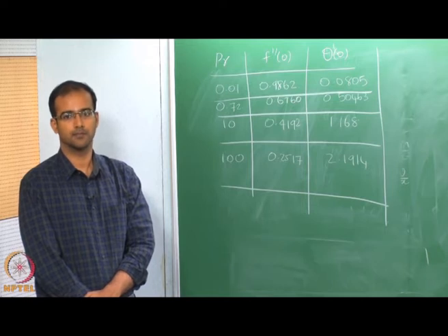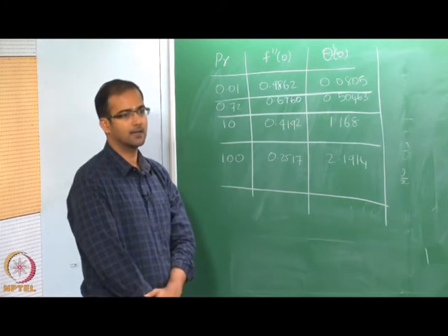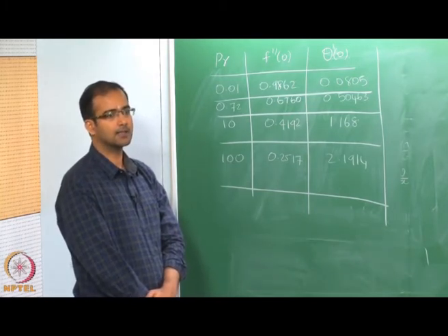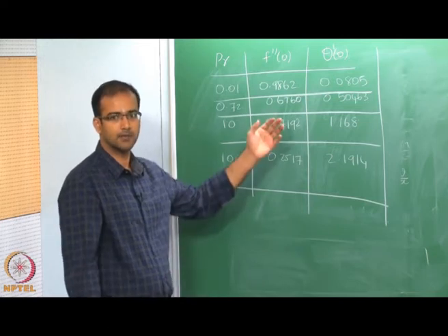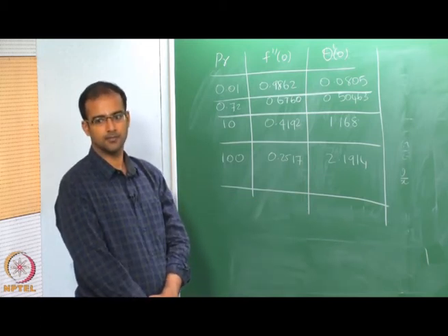That is also the same, 0.332. So, these values are now slightly higher than that, but it does not mean the final Nusselt number is going to be larger than the forced convection. We will see that. Now, we will convert that into an expression for Nusselt number.